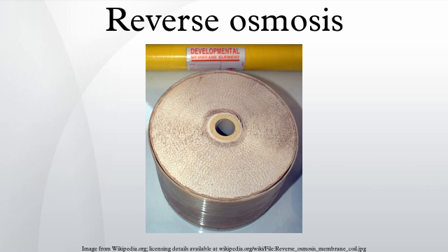Some small-scale desalination units use beach wells. They are usually drilled on the seashore in close vicinity to the ocean. These intake facilities are relatively simple to build, and the seawater they collect is pre-treated via slow filtration through the subsurface sand seabed formations in the area of source water extraction. Raw seawater collected using beach wells is often of better quality in terms of solids, silt, oil and grease, natural organic contamination and aquatic microorganisms, compared to open seawater intakes. Sometimes, beach intakes may also yield source water of lower salinity.